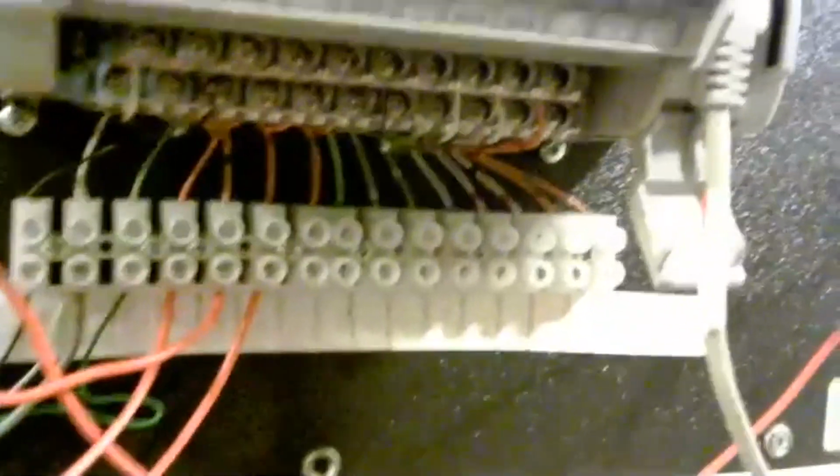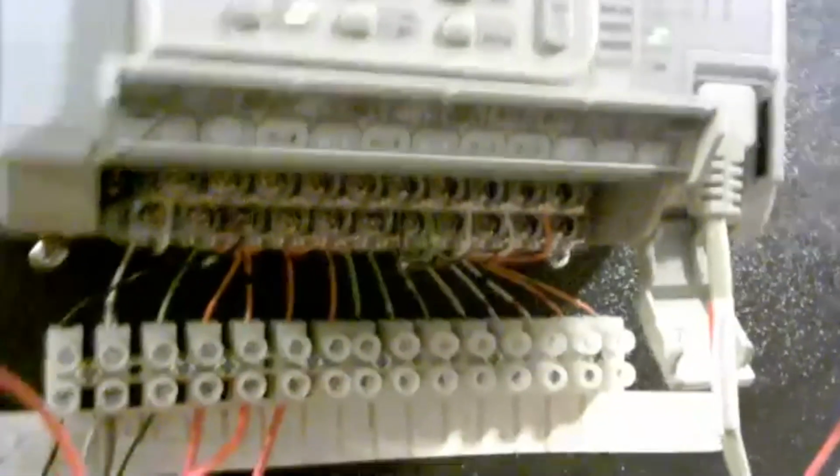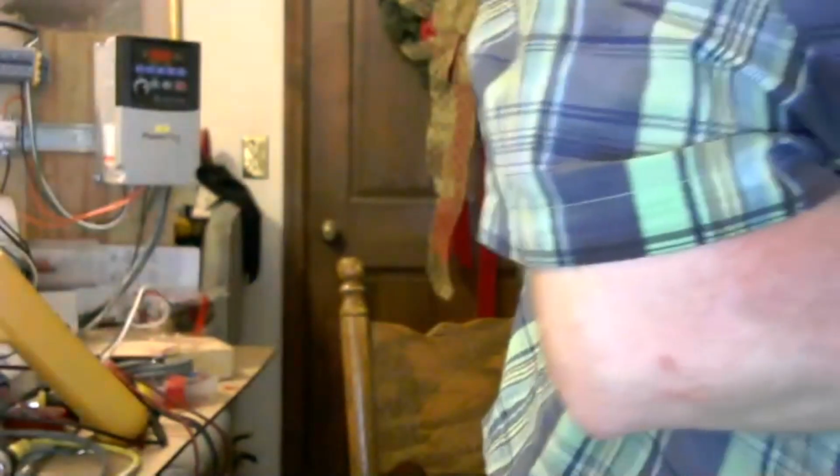And you would basically just fold, you know, you could let it all kind of fold down real easy. And if you're real easy with it, then you shouldn't lose any wires. But take a picture of everything before you undo anything, get you some good pictures. That's always a good idea before you get into something like this. And hopefully the wires would be labeled with wire numbers, but you don't always get that luxury. Whoever wired it, if they were in a hurry, may not have taken time to put numbers on the wires.